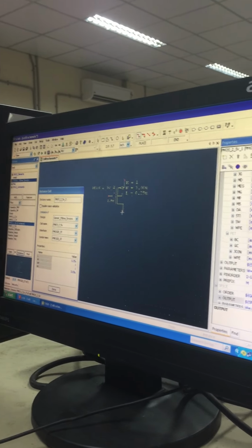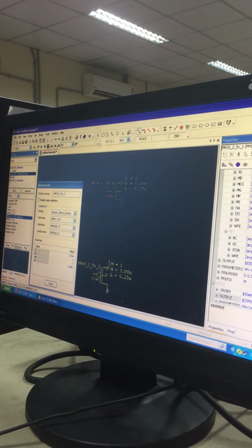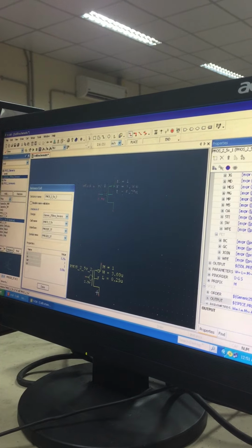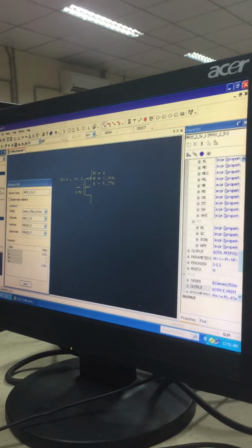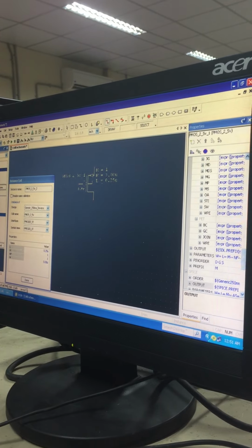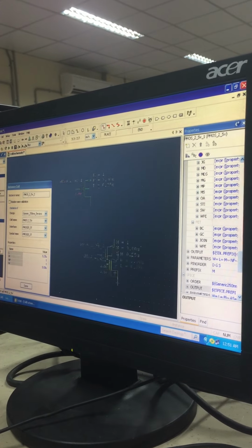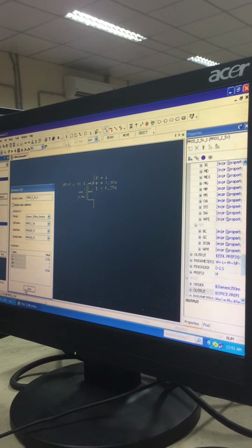And the other thing is, you can select any particular component and press and hold the scroll button. You should not scroll up and down. You have to press and hold the scroll button, and then you can move the mouse so that you can drag the component. Understood what I'm saying? If you want to drag a component and keep it somewhere else, you can just select it, go to this, first click, finish tab.